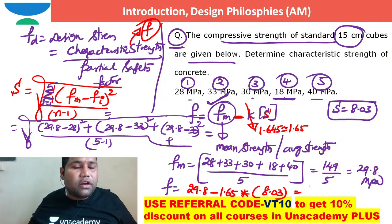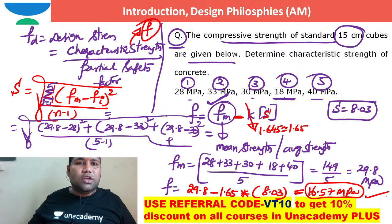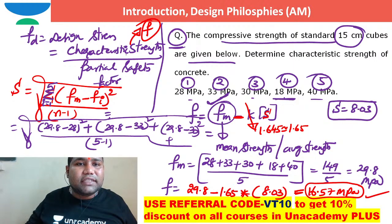If you work out the characteristic compressive strength, people usually call it Fck. The characteristic strength of concrete for these five observations is 16.57 megapascal.